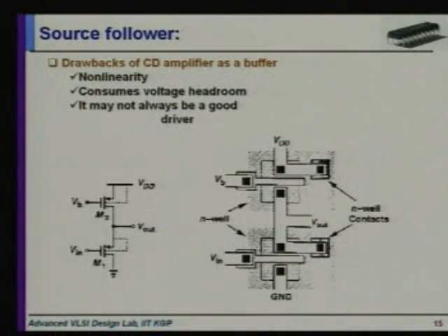And there is another problem: it may also not be good for a low impedance driver, because there is a problem with that particular voltage headroom. That is the same problem whenever we want to drive a transmission line, that is, from the antenna perspective. Then it is not very good as an amplifier or as a buffer stage.